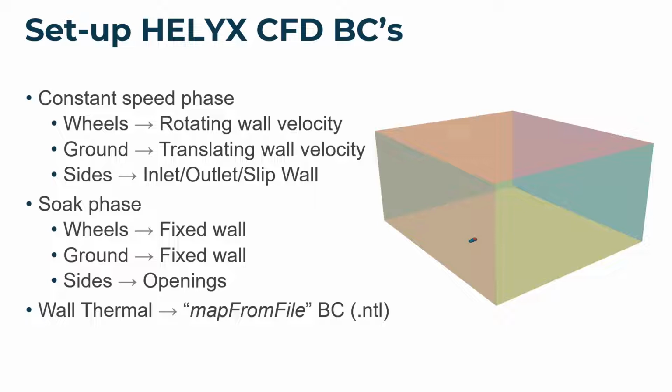On the wall, for the thermal boundary conditions, we use map from file, which is a boundary condition developed to read the NTL file written by TAITherm and to map the temperature into the CFD.